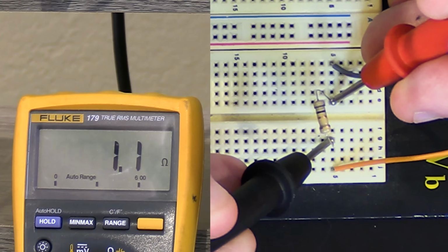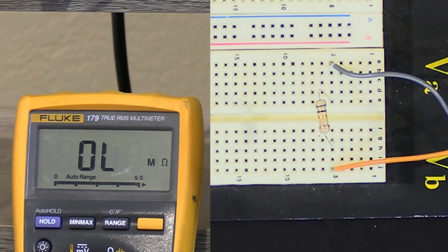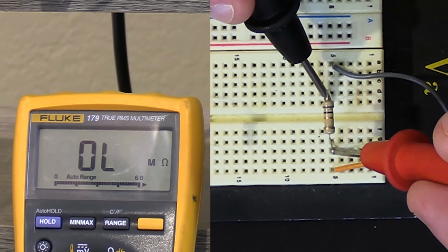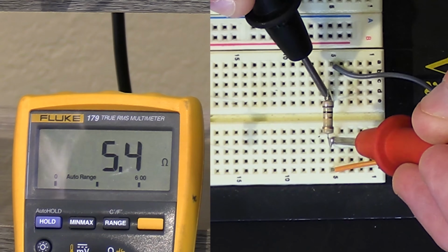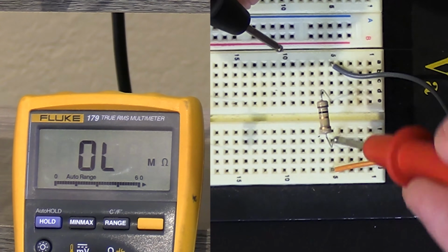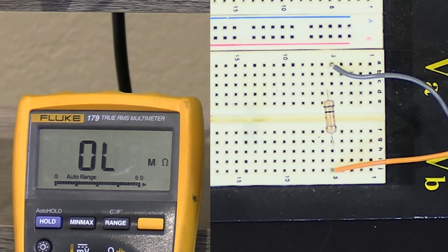This reads 1.1, 1.2 ohms. Now the actual value of this resistor is 1 ohm. It's not exactly 1 ohm for a couple of reasons. Because I'm touching it with this probe, I have a little bit of resistance in the contact point. And also, these resistors are not 100% accurate. There's a tolerance to all of them, so they're not exact values. The bands decode to tell me this is a 1 ohm resistance, but when I measure it, it's always going to be a little different than the theoretical value, but it's very, very close to 1 ohm. In fact, you can see it going down, down, down. If I push a little bit harder on it and really give a good contact point, you can see it gets down very close to 1 ohm.